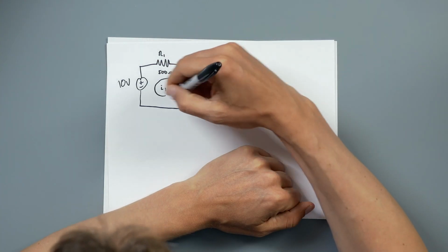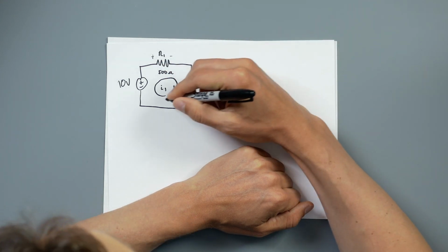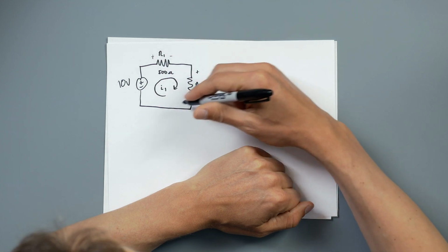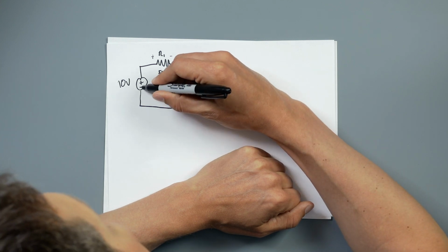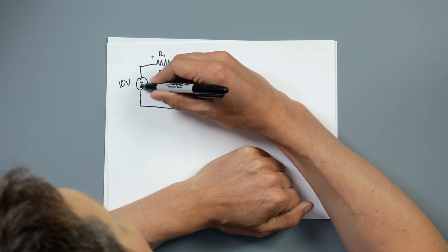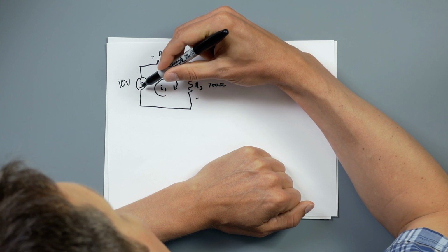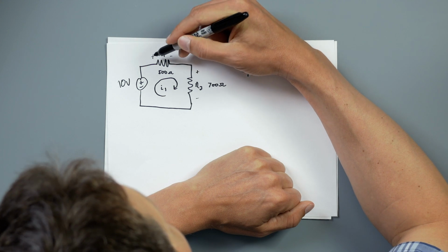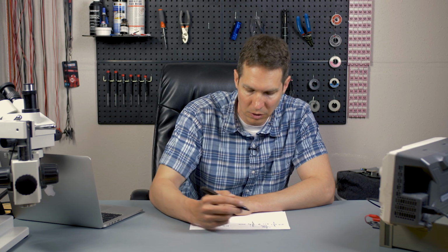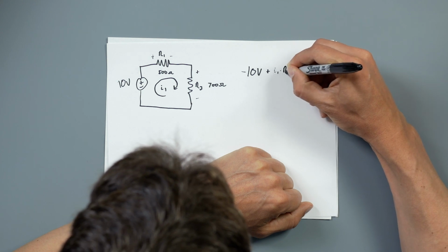So looking at this, you're assuming that current is flowing this way, so you're assuming that your voltage is dropping like this. So now as you are getting that current flow and you're creating your voltages, you will have that flow and you'll come up to this element and you'll say, I see a negative number there first. So my first thing will be negative 10 volts. And then as I keep on coming up here, I see that I have a positive there. So I'm going to be adding this voltage, which we know is equal to the current times the resistance. So this is just going to be I1 times R1.